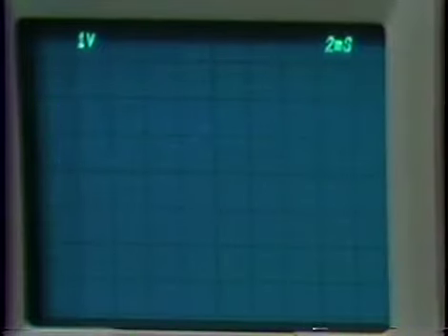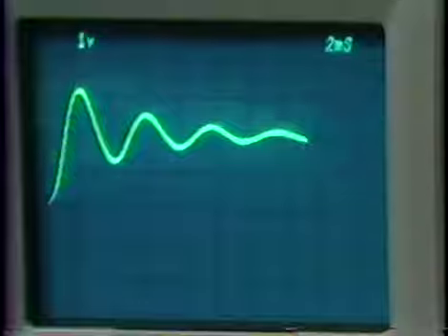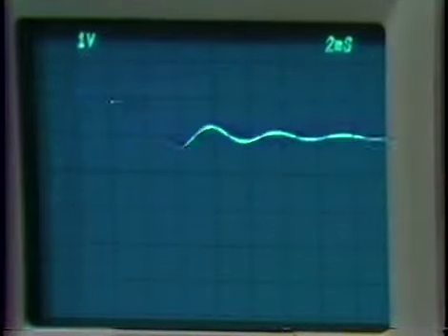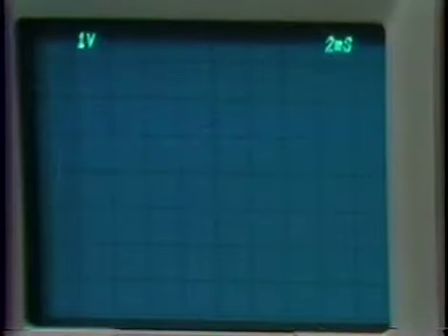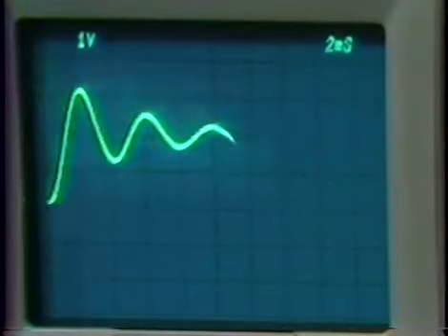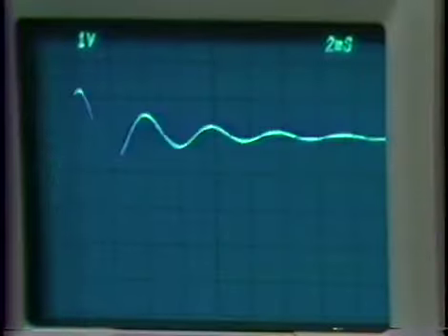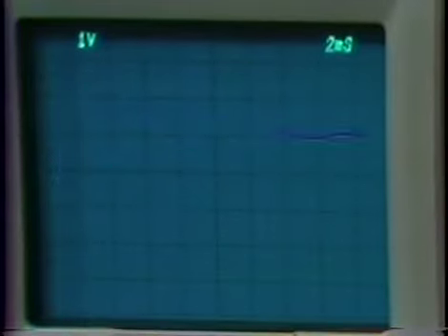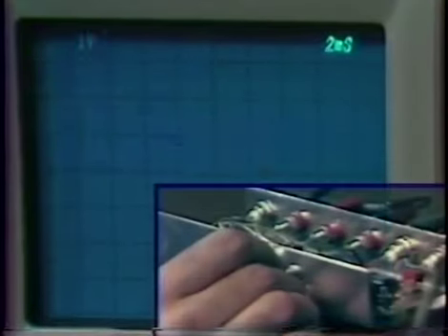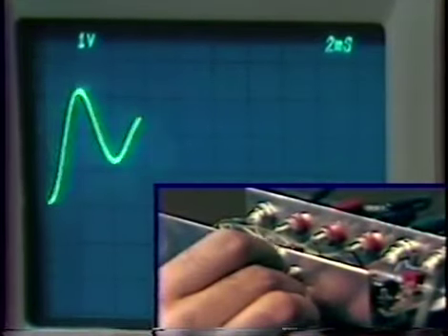So here we have a low value for A naught, less than the 2.4 critical value. The ring frequency, the crossover, occurs below the critical frequency, below 390 hertz. And we notice it's fairly poorly damped. There's relatively small phase margin for an A naught of 1.